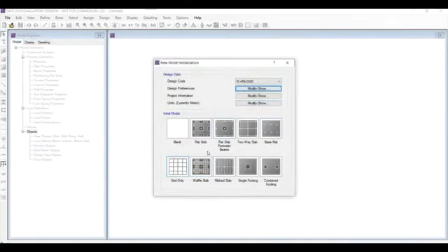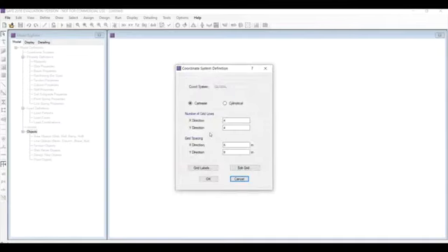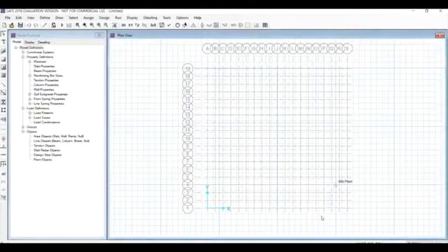And now go for grid only, as we don't have a mat foundation prescribed format, we have only base mat, but let's go for a grid only system so that we can have our own dimensions and our own columns. For an 18 by 18 meter mat foundation, we need at least 19 grid lines, if we take each 1 meter as one interval spacing of the grid line. So take x direction 1 meter spacing and y direction 1 meter spacing and click OK. Now we have the grid lines of our mat foundation.